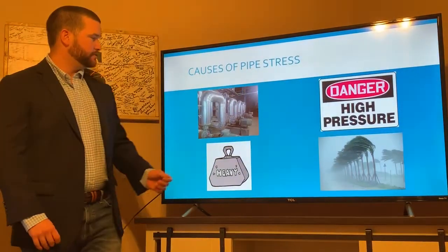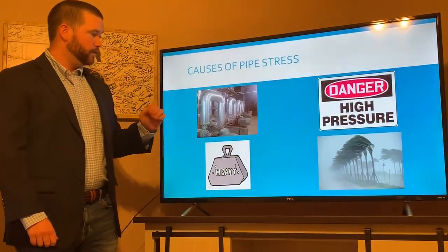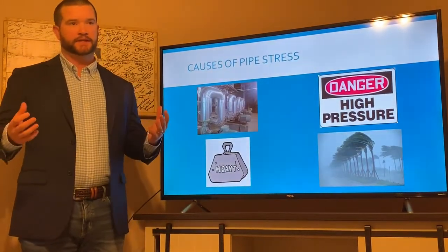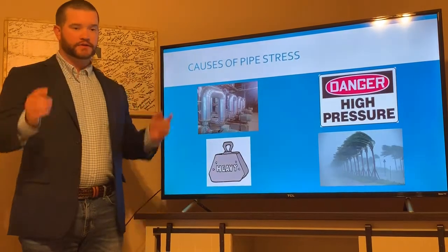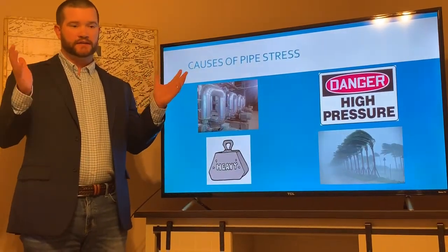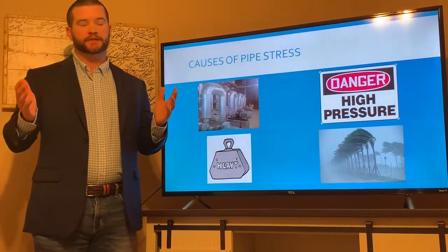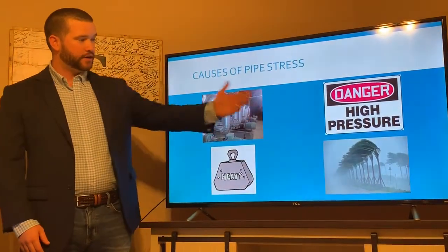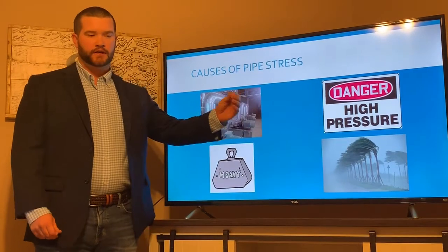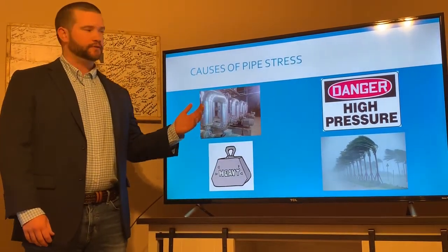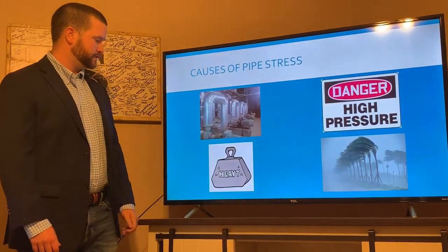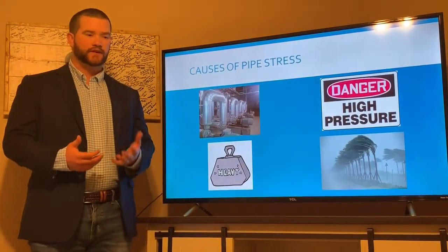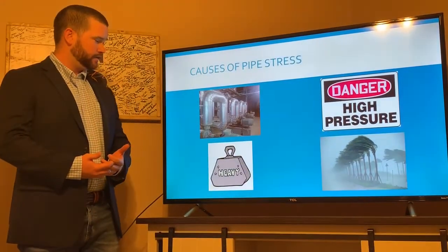So what causes pipe stress? One thing is temperature. Obviously, if you get things hot, they want to expand, and pipe that is routed in a certain way that tries to expand is going to resist that expansion, and the resistance causes stress within the pipe. Pressure can cause pipe stress, not to the same degree as temperature, but it does contribute to pipe stress. The weight of the pipe and the valves and the fittings that are on the pipe can cause pipe stress.